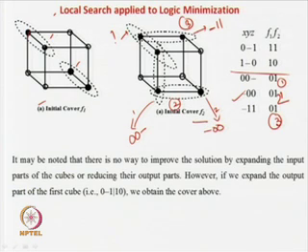So, if you try to eliminate something, it will start making clusters in this way or in this way, but you cannot have a cluster diagonally, because a cluster in the diagonal means there are two terms which are different. Like in this case it is 0 0 0 and in this case, say, x is 0 over here, y is 0 over here, z is 1 over here. So, you can see there are 2 bit differences between these 2 points. So, you cannot have something like this. There is no minimization possible in this case. Similarly, if this one does not exist, the same philosophy will hold.